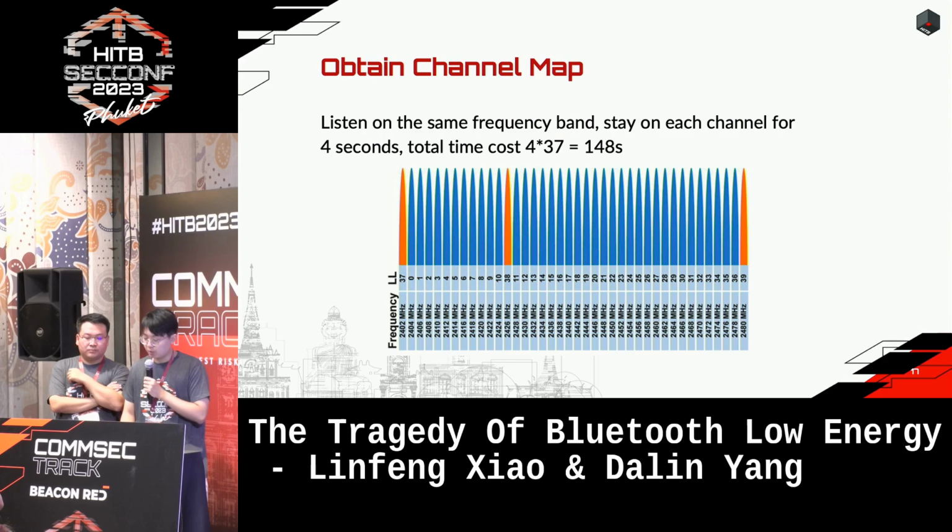The way to calculate the channel map is to listen on each possible frequency band for about 4 seconds. If there is the access address characteristic we are tracking, we record it. In total, it takes 148 seconds to acquire the complete channel map.